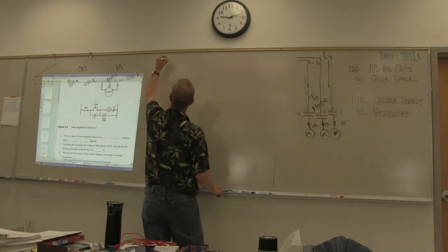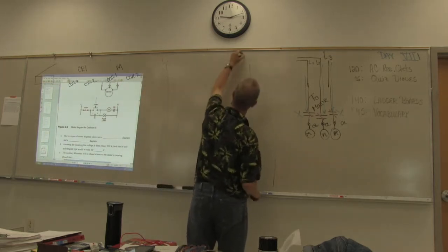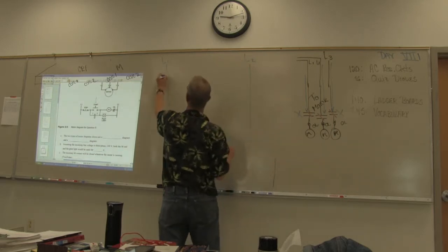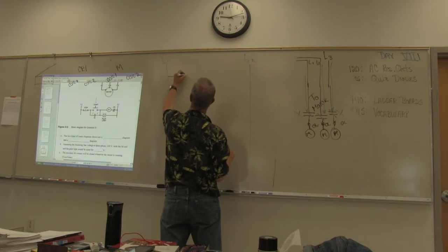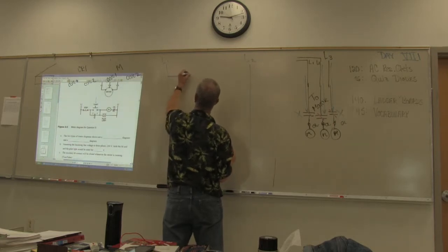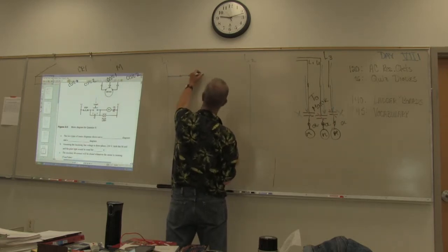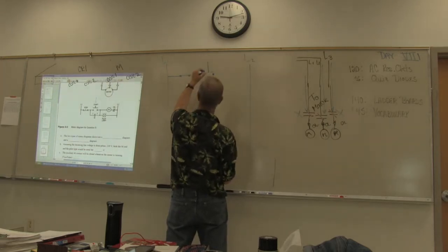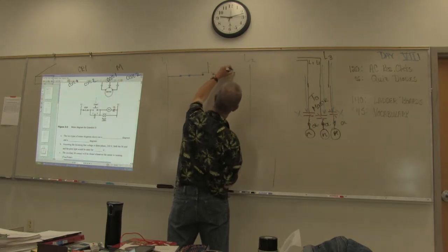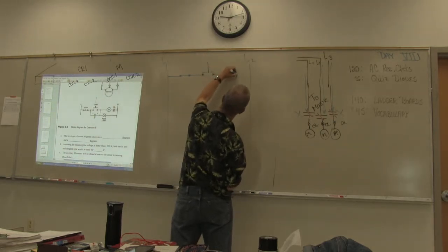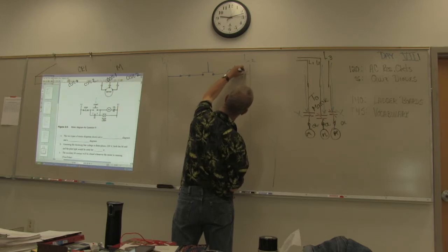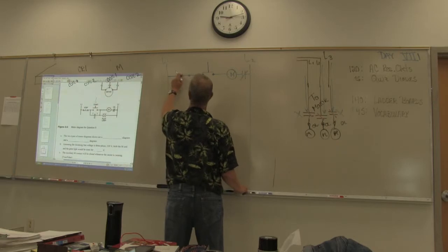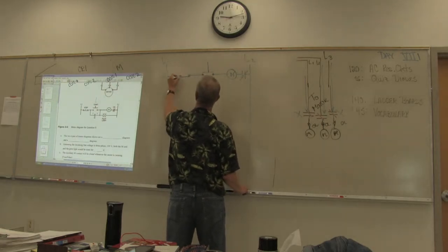So once that switch is pushed, all the current will flow, and then it'll reverse the contact down there on your wire 2 and 3. Well, I guess the way I'm looking at it, it could bypass the start button. And why doesn't the power, when it gets there, energize it? It can't bypass the start button. I don't know where you're getting that from. Well, I don't understand why, if the power gets to the contactor, it doesn't energize the contactor. It does energize the contactor. That's the part that you're missing.